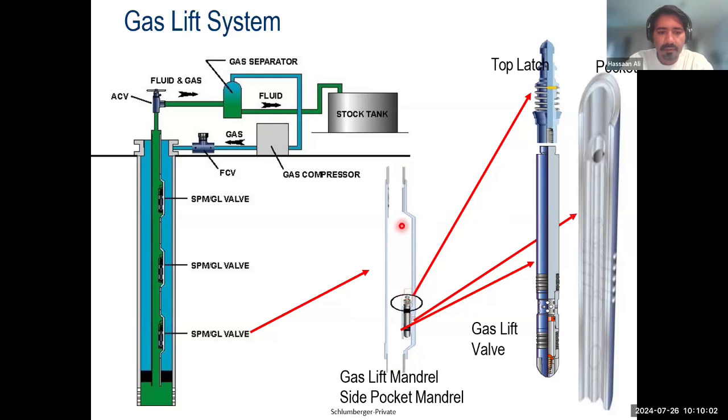So once the gas lift mandrels are deployed in the downhole, we can actually send an intervention tool down through a slickline or a wireline rig or a wireline unit, and we can actually pull this valve for maintenance or changeover.